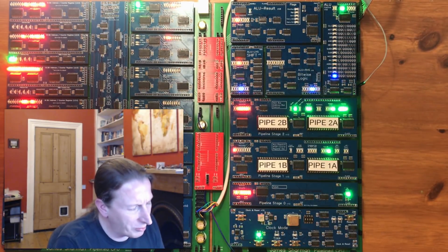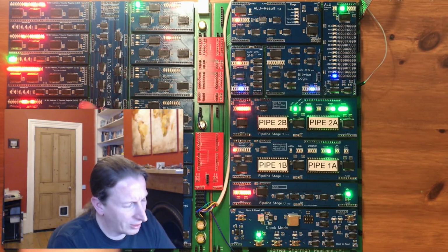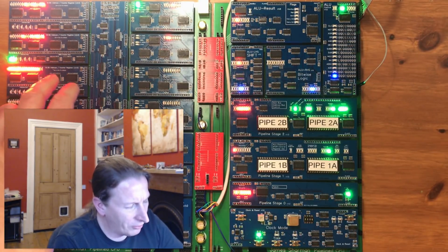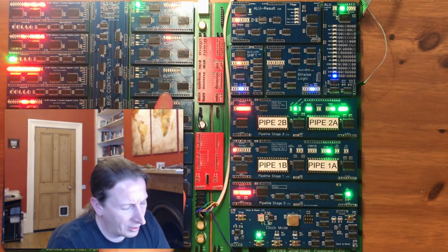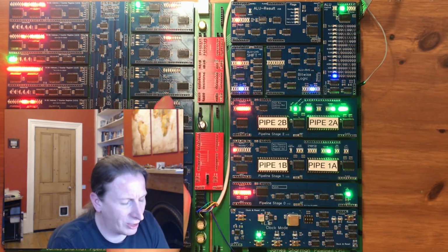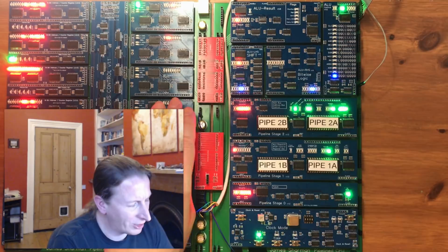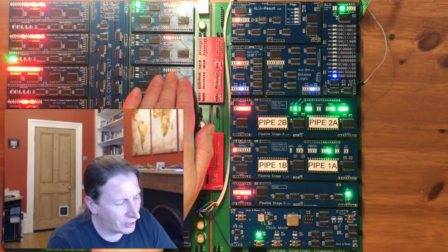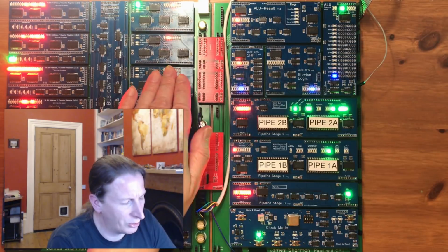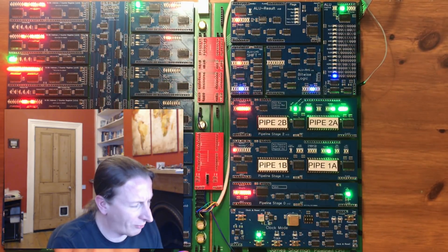But I did come up with a realization that when I'm doing a 16-bit move, I'm never actually dispatching an ALU operation. And the LHS and the RHS between them form 16 bits of data. So if I actually made it so that the transfer bus and LHS, RHS were using the same lines, then I could take advantage of that in a few other ways.